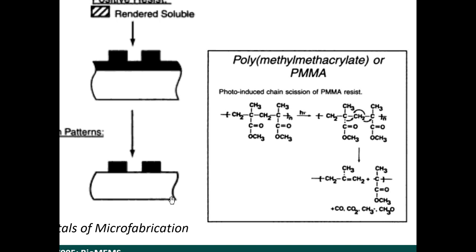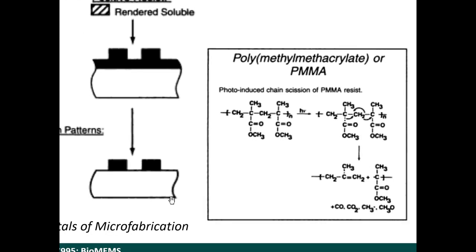So you can see from this chemical diagram that when this molecule, shown on the left, is exposed to ultraviolet light, it undergoes a chemical transformation in these carbon bonds here that cause it to break into two separate groups. Okay, and when it breaks into those two separate groups, now the material has become soluble in developers. When you dip it in the developer solution, this disappears.